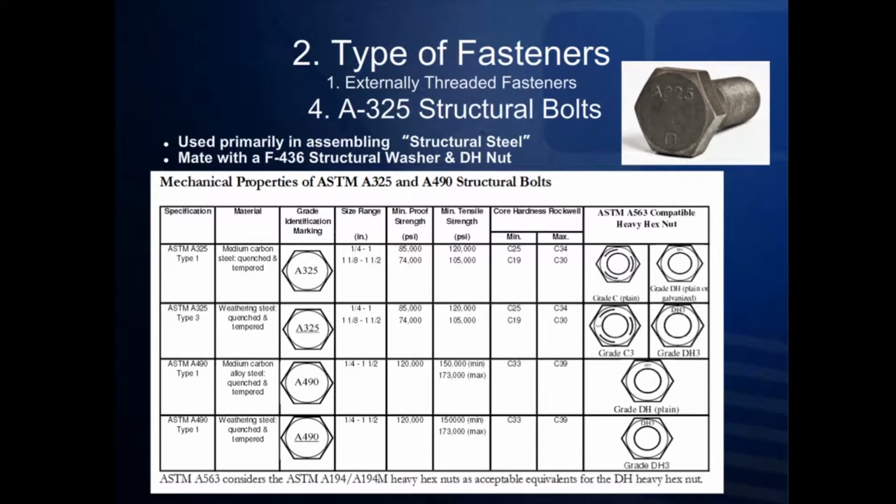This begs the question, should an SAE J429 grade 5 be substituted for a structural bolt? The answer is no. This is also the case when comparing a grade 8 to an A490. They're just not the same, and here's some reasons why.